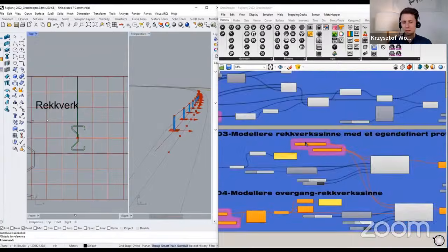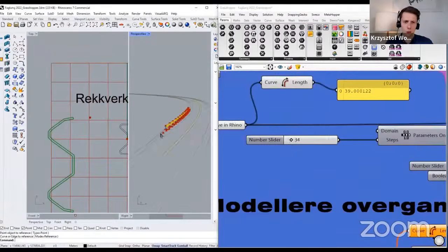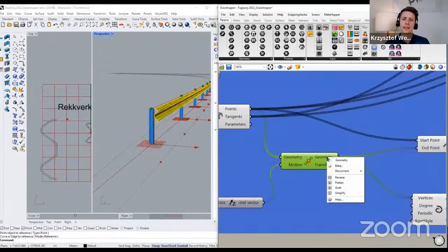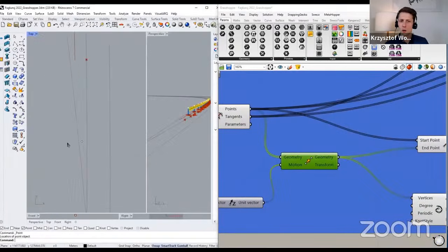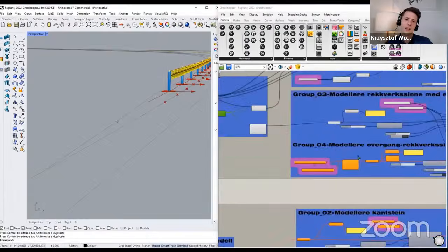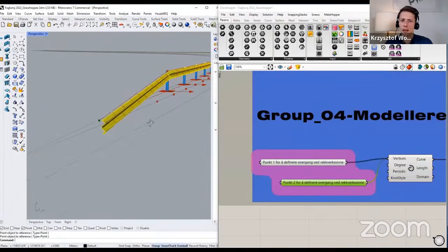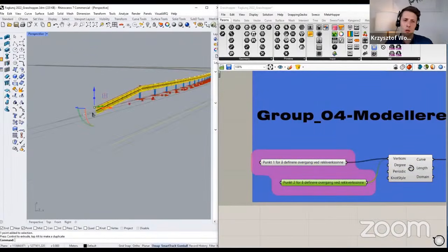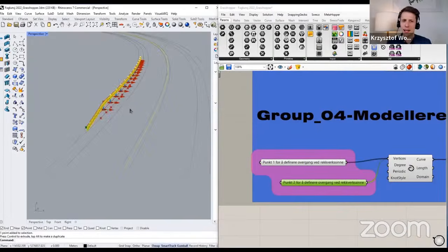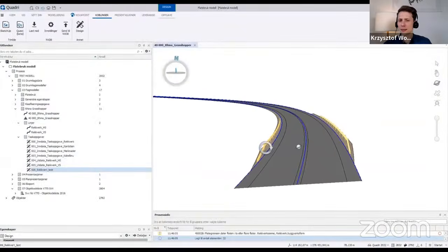So we can divide the line by the barrier's columns, and afterwards you can define the shape of the whole barrier and define the whole length. At the end, with a point, you define how the ending of this barrier will look, and we can apply the same on the other side.